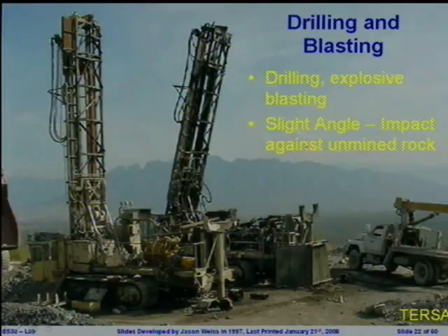detonated. They will typically have a slight angle to the detonation, and the slight angle is to drive the force of the blast back into the face of the rock. So rather than blasting to shoot everything out across the quarry, they are trying to get the energy to go back into the rock and trying to drop that rock straight down because it's a lot easier to pick that